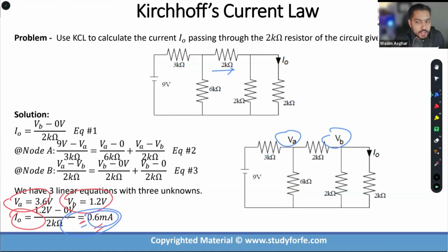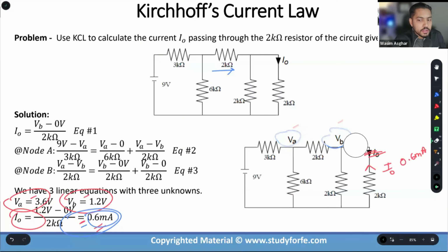The negative sign is saying that in reality, and this is hypothetical, the solution is not minus 0.6, it is 0.6 positive. But assuming that it was minus 0.6 milliamps, what it basically means is that you simply have to switch this. The current is actually flowing upwards. A current of 0.6 milliamps is actually flowing upwards rather than downwards. That's it. And if you end up with negative signs for voltages, you don't do anything. That is actually a negative voltage here and a negative voltage here, if that was the case. Exception handling is only done for the currents.